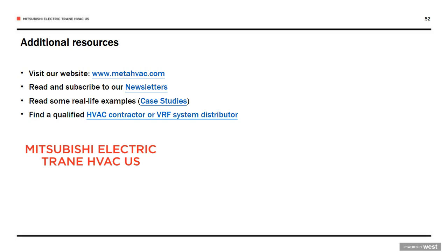In the northern climates, most of the time we're dictated by actually the heating loads, simply because if we can provide enough heat for the system, the cooling is no problem. So question number one when working with engineers is, what are your loads? Question number two is, what style of indoor units do you want? Question number three is, how do we want to zone everything?